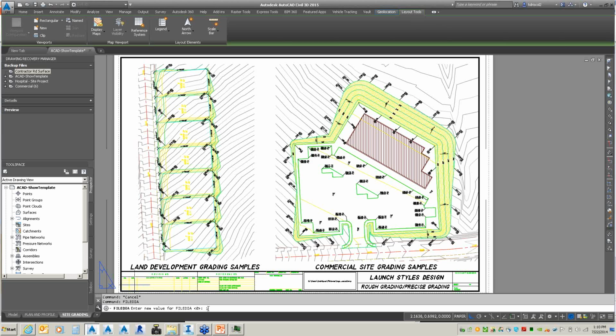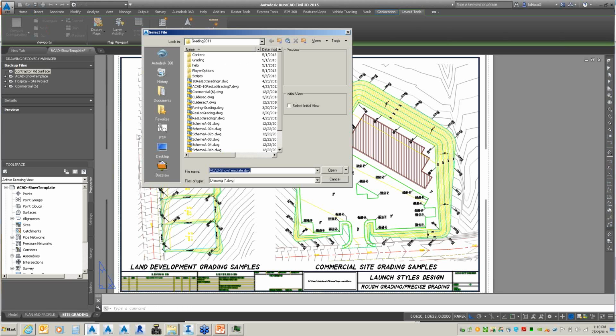It's a system variable in CAD. Anytime you lose your dialog boxes, that may reset to 0. It needs to be set to 1. And then you can come right back up, and now you have all your dialog boxes. That's just a tip for today.